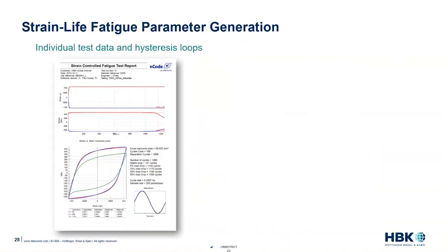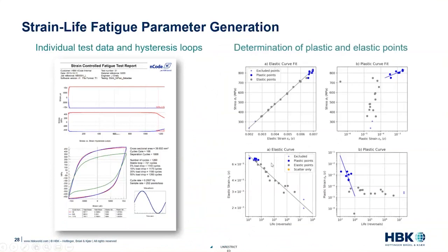So that's used to give reports for each fatigue test. We do the post-processing to identify the load drop, so we can actually see the load dropping here. We determine whether that specific test is a plastic or elastic failure, and characterize the curves from that.